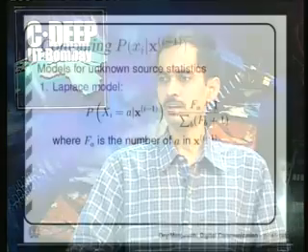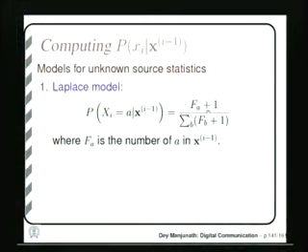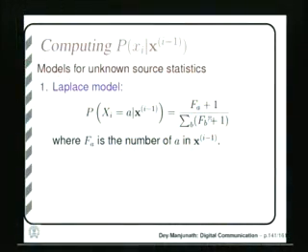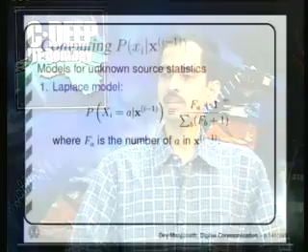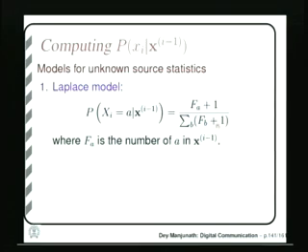Why are these ones kept here? This is because initially you should not have 0 by 0. If you have received 0 symbols, when you are taking i equal to 1, you have received 0 symbols. So, FA, FB, all these are zeros. So, you are taking basically a uniform distribution in such a case. Initially you are assuming a uniform distribution. For binary you will assume 0 with probability half, 1 with probability half. So, that is the initial distribution we are taking, and then if you have received 0 in the first symbol, automatically we weight 0 more, we assume that 0 has higher probability.